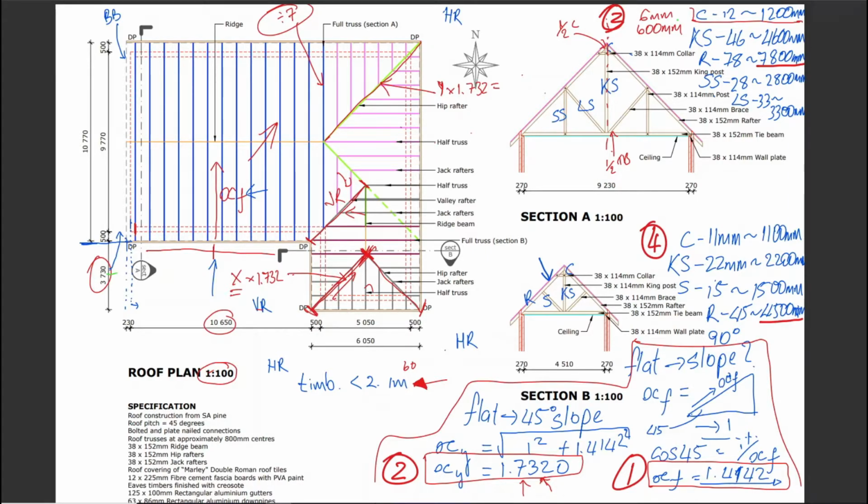It looks like half of X. And it is not. And I'll tell you why. We're going to work with these divisions here again, right? These divisions are really useful. So not only do they help us divide a full rafter like that, but also you can see that there are nice divisions here on your hip rafter, right?